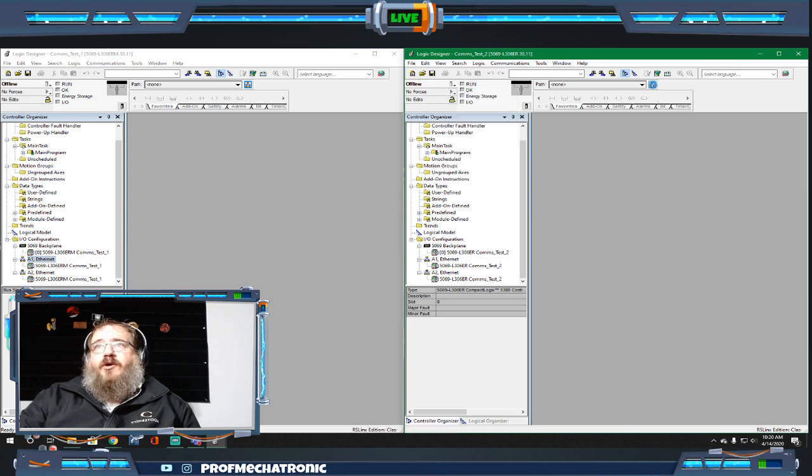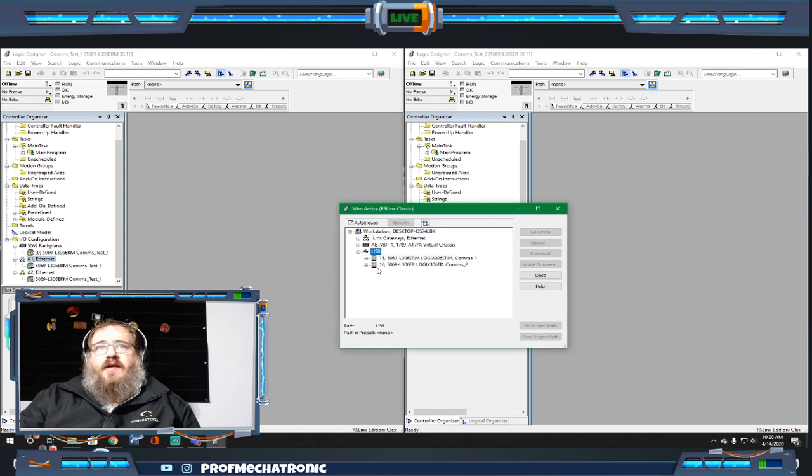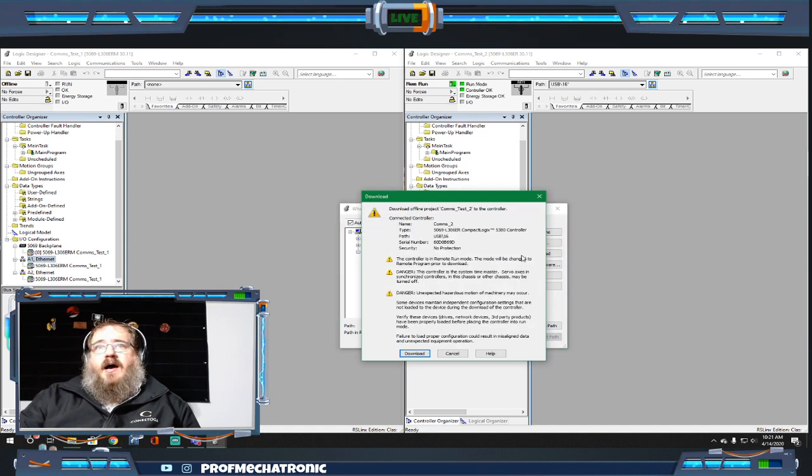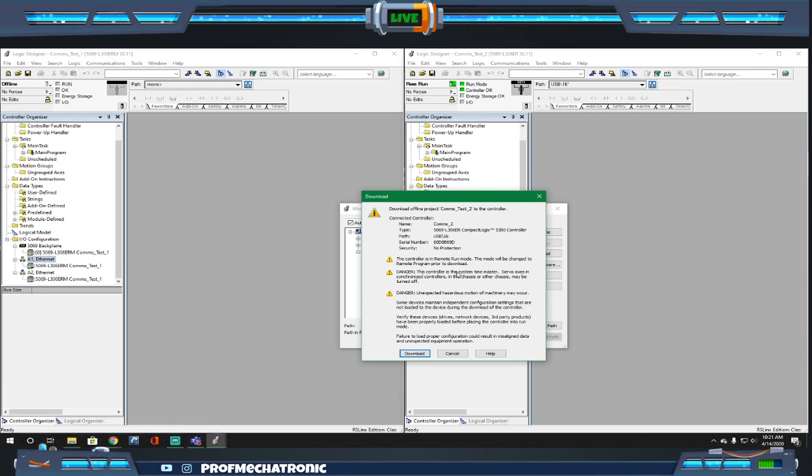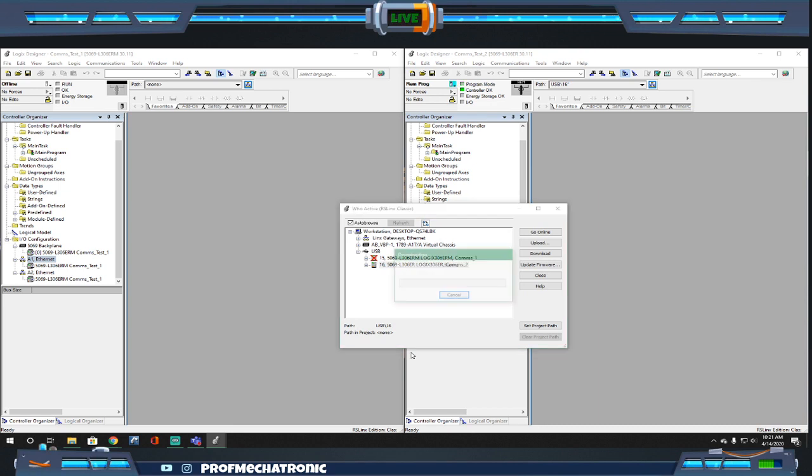So here again, we're going to go to Who Active. This one we do definitely know communicates. There's the L306ER. So we're going to take comms test 2 and download that to our PLC. So from that PLC, we're going to hit the download button. We will then send out the information.